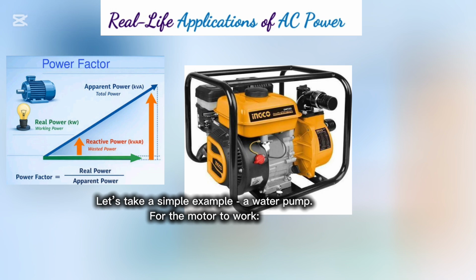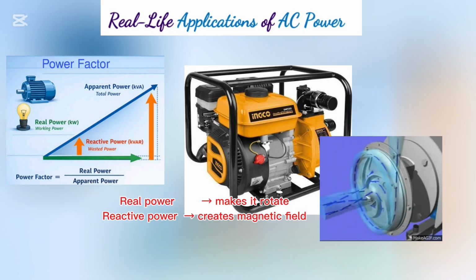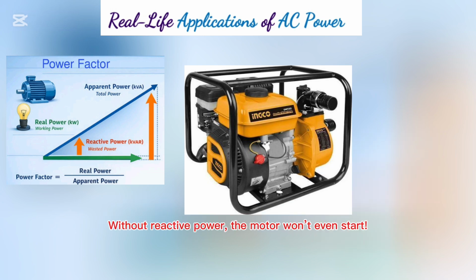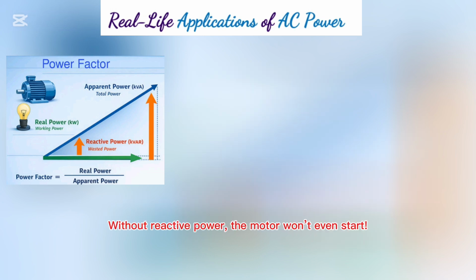Let's take a simple example, a water pump. For the motor to work, real power makes it rotate. Reactive power creates the magnetic field. Without reactive power, the motor won't even start.